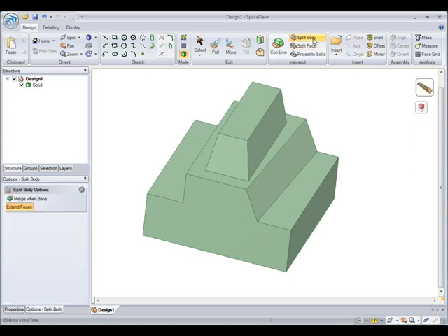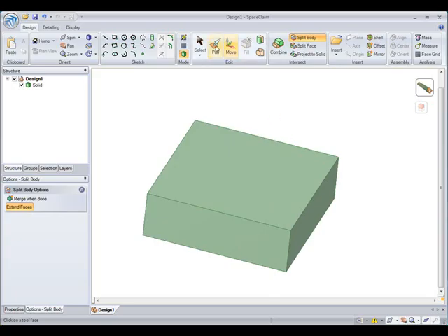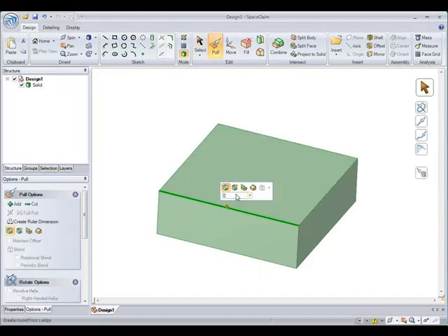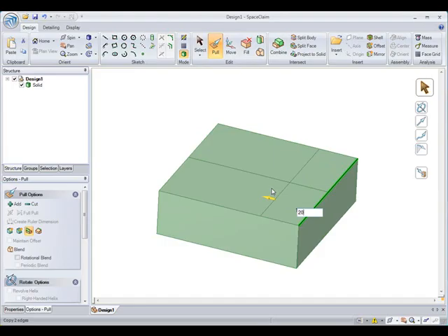But now let's cut off the top of that block, and we'll see another way I can use extrude edge and pivot edge. I'll use extrude edge and copy these edges inwards. I'll make them 20, and I'll do the same to the other side and copy that in 20, so I have it running down the center.